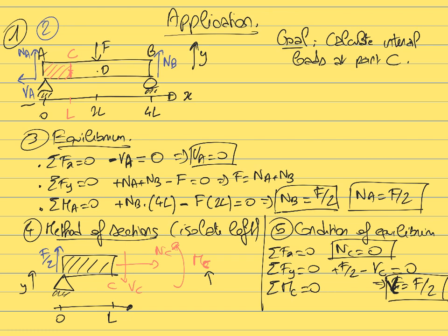First, we have the moment MC that is applied by the right to the left. So this moment here. Now we need to write the sum of the projection. MC is an anti-clockwise moment, so it has a positive projection, so it's plus MC.